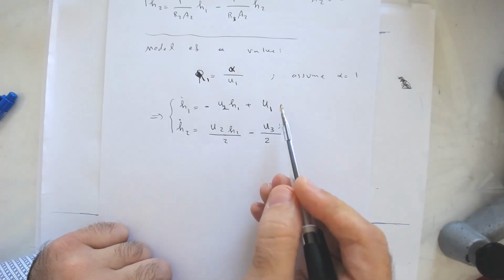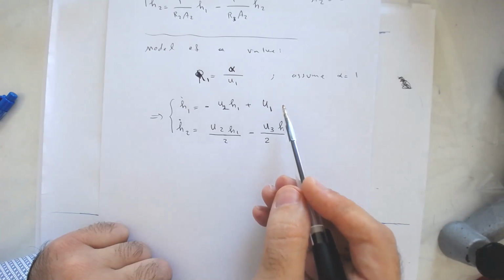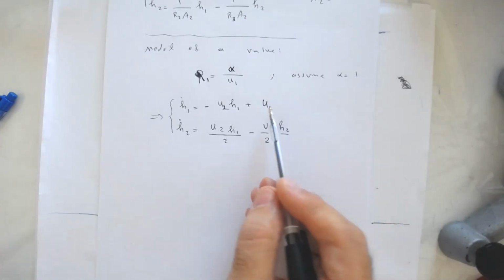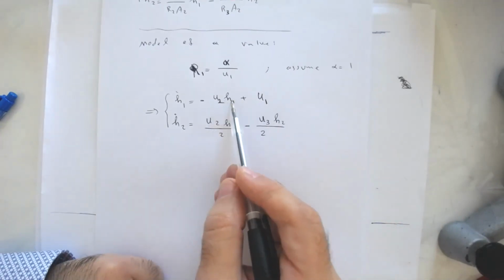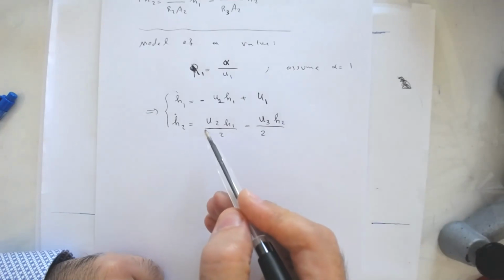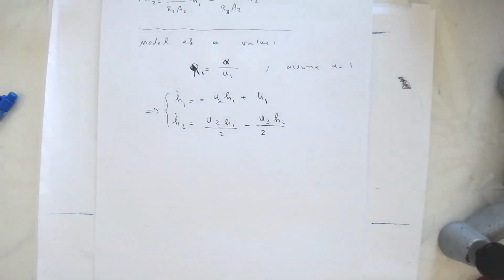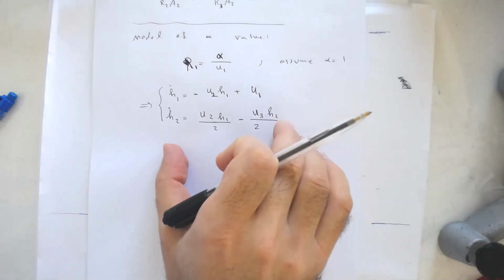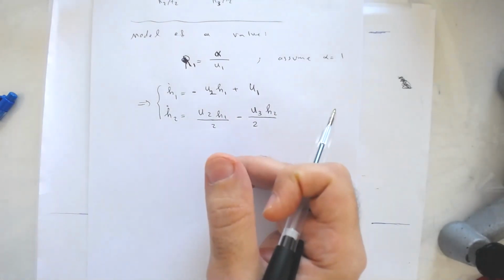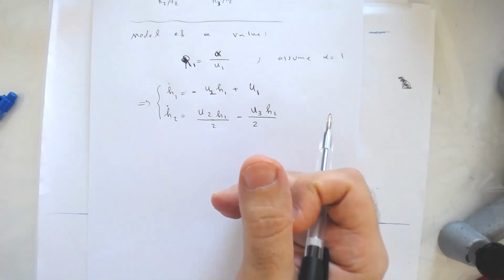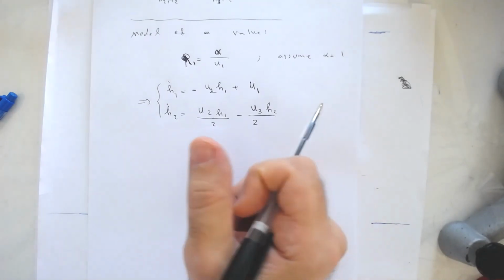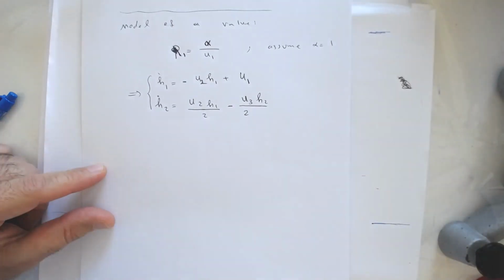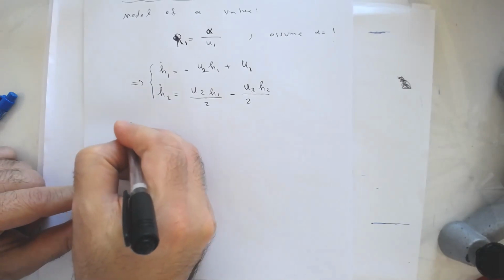But the system is nonlinear. Okay. So even though we assume that the model of the valve is linear, because we have multiplication of input and state, we have a nonlinear model. So what I'm asking you is to model this system in Simulink, also to linearize it, and then we try to design a controller for that. Or maybe I can linearize the model here as well. So let's linearize it here, and then we go to the simulation.